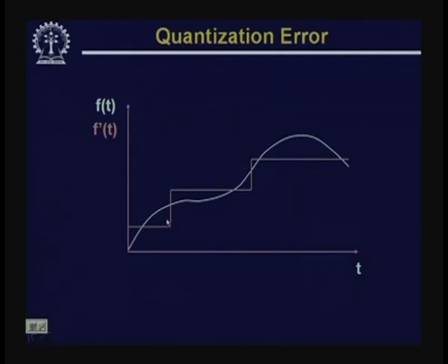So, we are always introducing some error in the reconstructed signal which can never be recovered, and this particular error is known as quantization error or quantization noise. Obviously, the quantization error will be reduced if the quantizer step size, that is the transition interval T k to T k plus 1, reduces. Similarly, the reconstruction step size R k to R k plus 1 is also reduced.